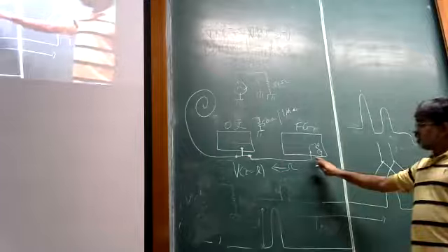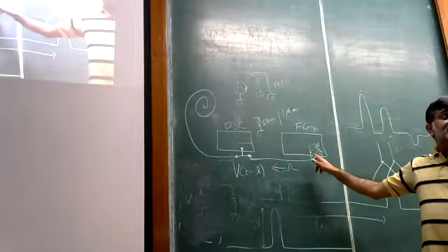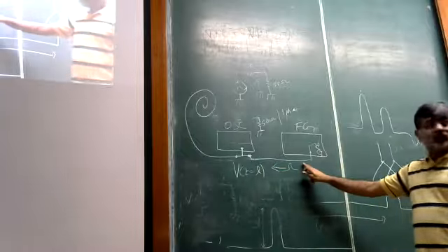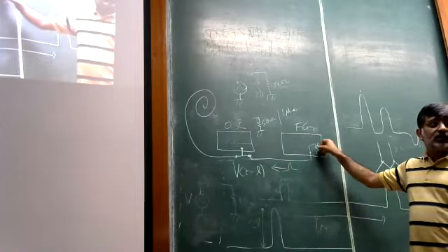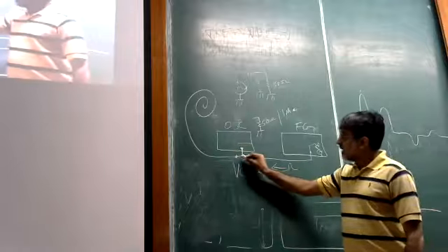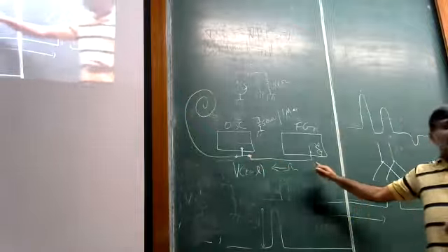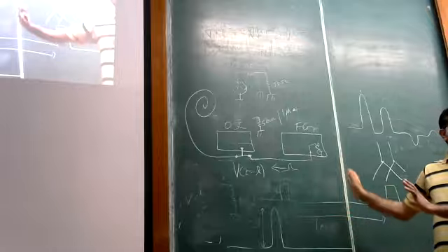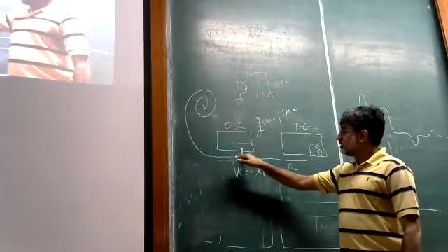But the transmitted part can actually be forgotten. So the one thing you said that was not correct is that the function generator is matched. Remember that for the wave which travels here, the mismatch only matters if this cable's characteristic impedance is different. It's not that there is a different load here. So the returning pulse here will experience a reflection and a transmission, but whatever gets transmitted here is absorbed by the 50 ohm load, so that never comes back. So we can completely ignore what is happening to the transmitted wave. The only thing which matters is what's going on here.